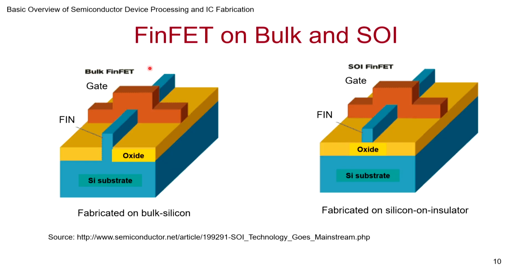So first, I would like to show the structure of FinFET up close. You have already seen it. You have silicon substrate. On top of it will be oxide, and somehow the fin will be jutting out. And at some point of the fin, you will put the gate poly on top of a thin oxide that is formed around the fin. This is how a classic FinFET structure is supposed to be. But notice here that in this classic structure, which is what Intel ended up using, you have silicon substrate and the fin is directly touching that. So this is how it is done.